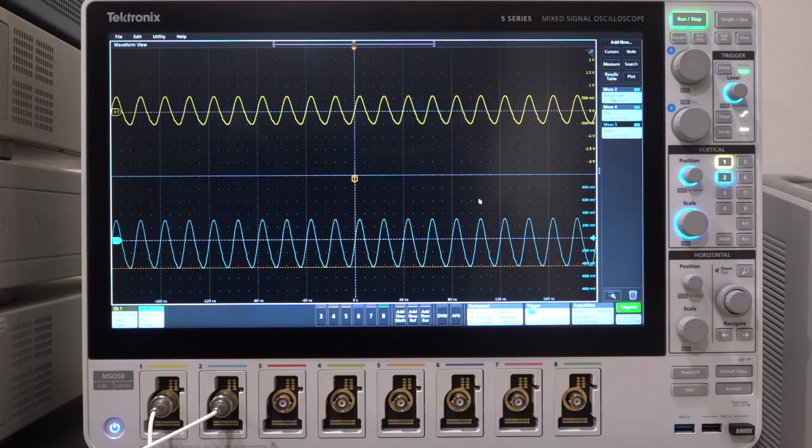Now, it's not supposed to replace an oscilloscope, of course. It is supposed to help you catch an issue when you don't have an oscilloscope handy at the input of the DUT, to make sure that the signal that's being applied is very close to what you expect it to be. And this can be very handy without occupying an input of an oscilloscope and without having to disturb the input of the DUT.